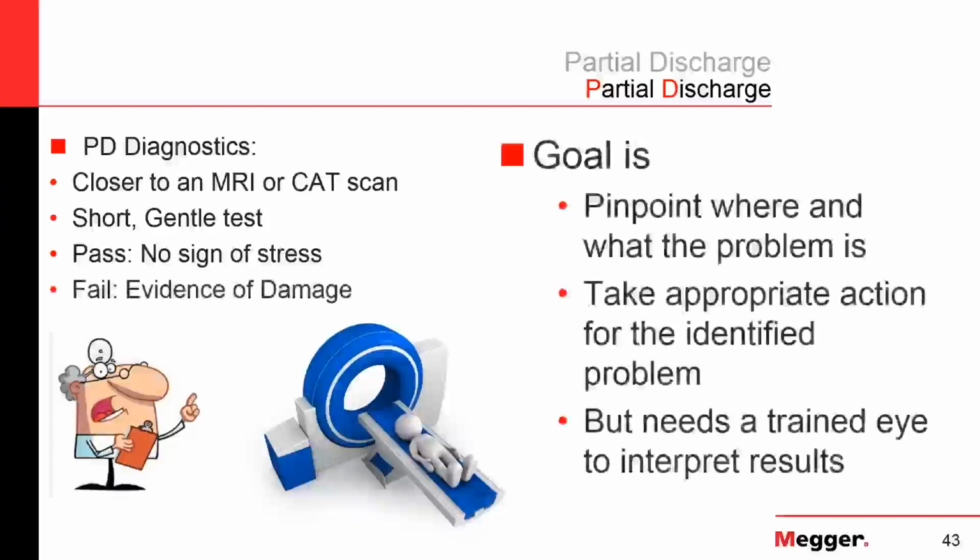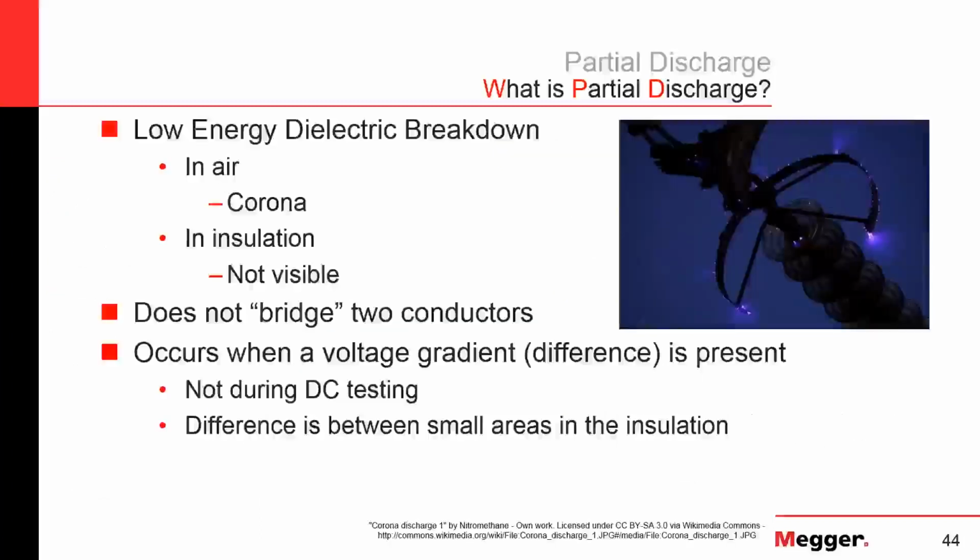And the goal of partial discharge testing is to pinpoint where the problem is, possibly what the problem is immediately, take appropriate action for the problem you found, and you can do all that, but it does need a trained eye to interpret the results. The training requirements aren't severe, but there are some.